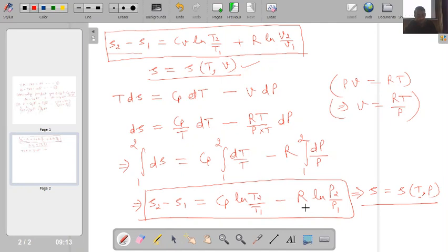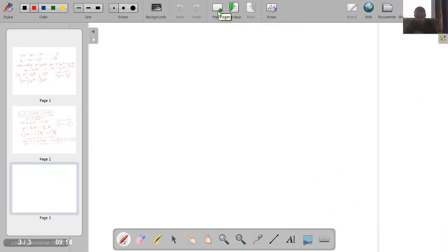Okay, so now we will try to utilize these two important relations to determine the property functional relationships for isentropic processes. Okay, so if you do remember, I have told in the previous lecture that an isentropic process is something where we have nothing but ds equal to 0. So the meaning of ds equal to 0 is that if the process is undergoing from state points 1 to 2, then I can simply say that S1 is equal to S2, and using the generalized correlation